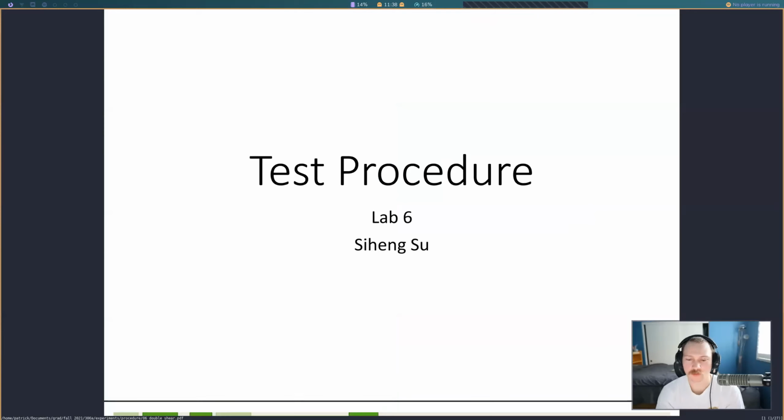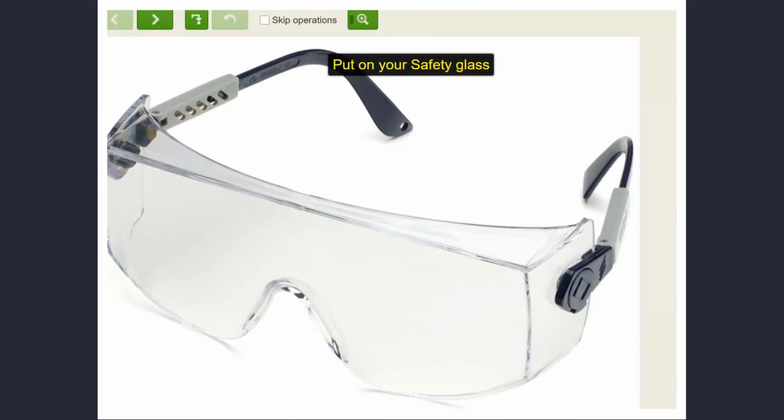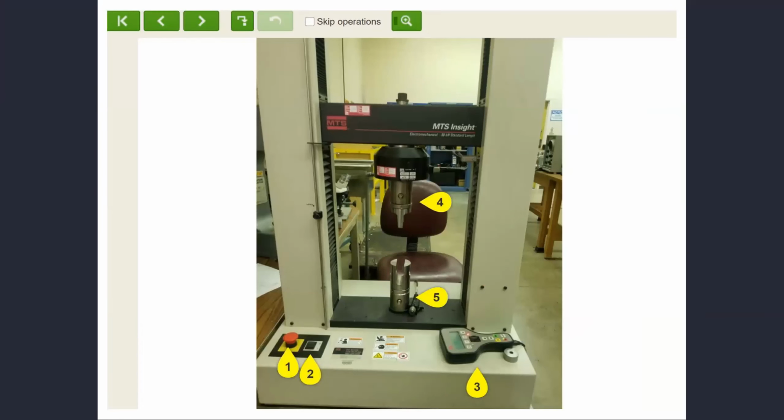All right, so the 6th lab. This is the Double Shear Lab. So this is what the setup is going to look like in the actual lab. So we have different fixtures on the MTS tensile testing machine. This top jaw here, it's going to be going down into this bottom jaw. We're going to have a little rod that goes through here. And as this pushes down, we're going to have shear failure right here and another shear failure right there.